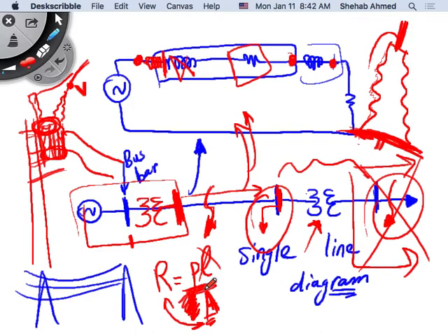So if it's a heavy cable, you build something that has a very small resistance so that you can reduce power losses. But it's this big, right? How big of a tower do you need to carry 3 of those? Huge towers, very expensive towers, lots of space, etc. So it's an optimization problem. We're always going to be optimizing in a power system. So voltage levels are going to be something that you will decide based on an optimization problem.